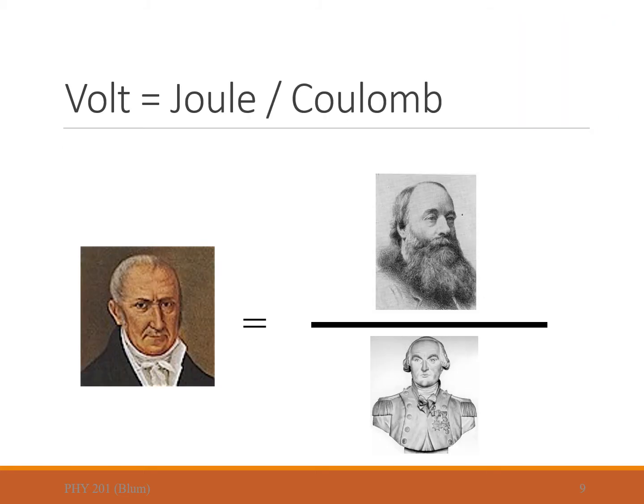So again, a battery is characterized by its voltage. It has an arrangement of charges that have an energy. Because it's charges that are causing that energy, or that energy change when they rearrange, it is convenient to define an energy per charge, or a joule per Coulomb, and that gives us our unit of volt as the unit describing a battery.